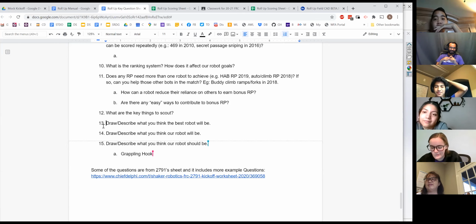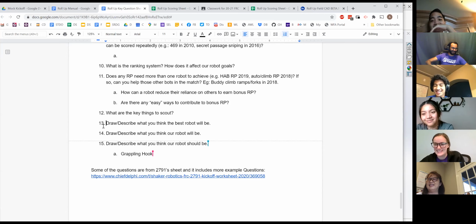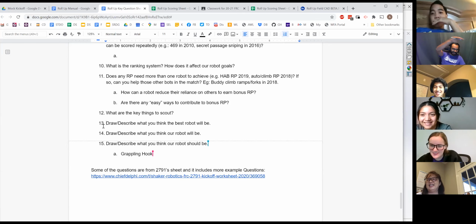And then there are really weird ideas of how do you get stuff out of below 18 inches if you want to hold as much ball as possible. Do you move your gearboxes above 18 inches? Do you move your battery? Everything you normally would put below 18 inches, and just have a giant empty box with some wheels down there? The entire belly pan is an elevator. No, it's not an elevator, it just starts up there. Oh, that's even weirder. Everything below is just empty space for balls.